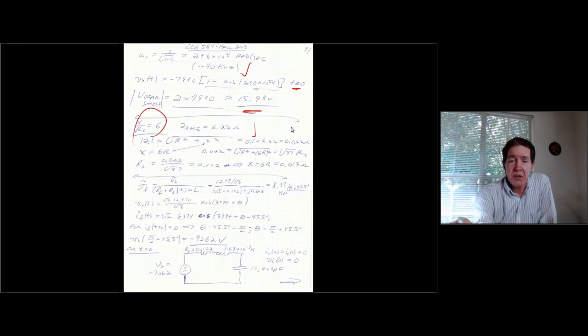Again, we convert that to ohms, but this time it equates to the square root of R squared plus X squared. From the X to R ratio, we know that X is 6 times R. Substitute in, and we get an expression for calculating R sub S for the substation or the source, and then X is 6 times this value right here.